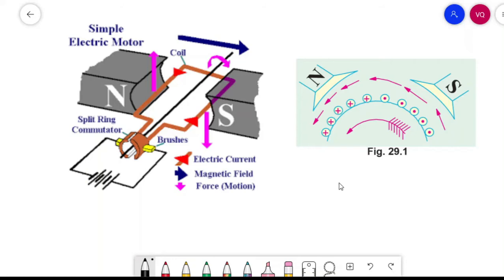These forces collectively produce a driving torque, which sets the armature rotating. It should be noted that the function of a commutator in the motor is the same as in the generator. By reversing current in each conductor as it passes from one pole to another, it helps to develop a continuous and unidirectional torque.